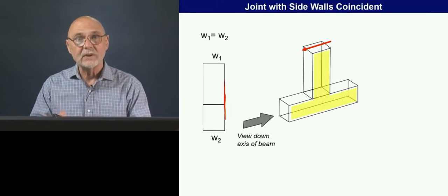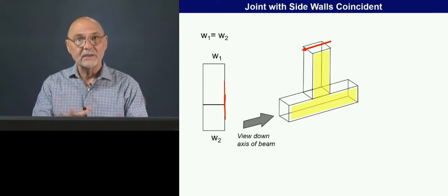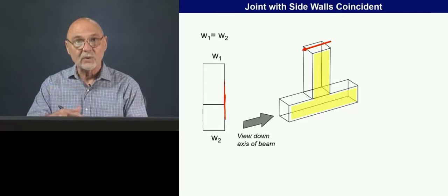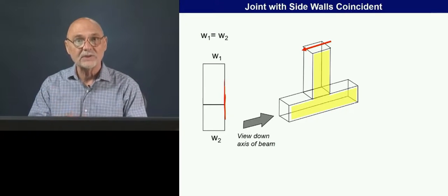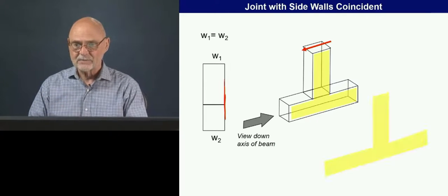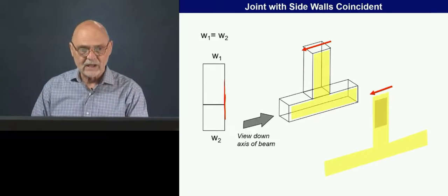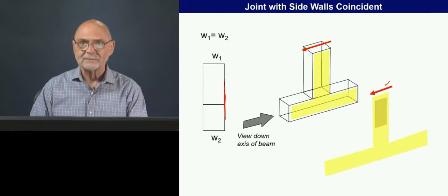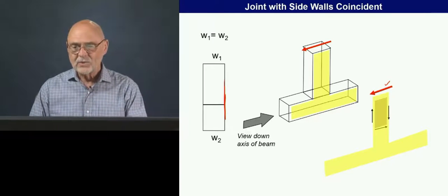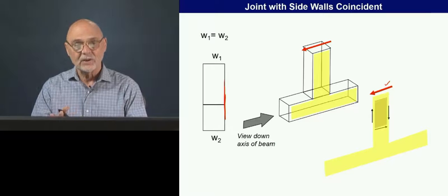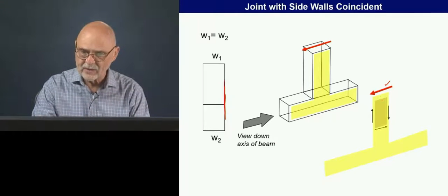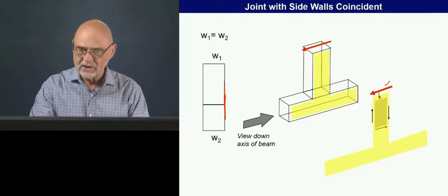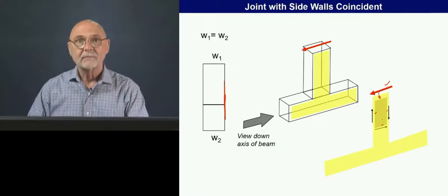So let's do what we did when we looked at the body in bending and flowing down requirements. If you remember, we idealized the structure with some simple structural members. So we're going to use the same ones, bars and surface elements. So here's a surface element, and here's the load that we're applying. We saw that a surface element could only be loaded by loads in its plane. So here's the applied load on the top here. So we need to generate these edge forces.